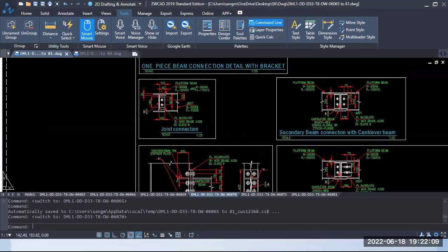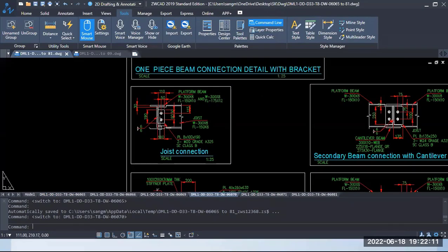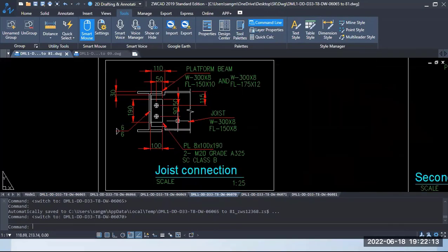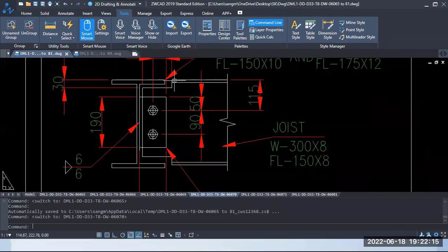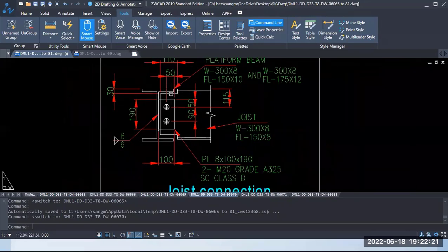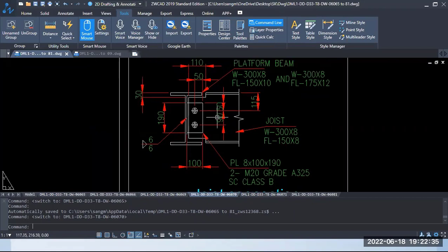So this is the joist connection that we have seen. This is the complete shear connection, and this is the coping of the beam to accommodate this member to this depth. We have cut this I section member, and this is the coping. There are certain calculations we need to perform as per American code, because in Indian codes we do not have much provision for the connecting elements and connections.